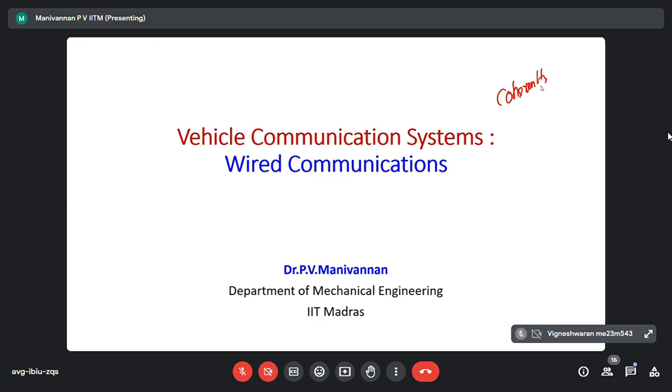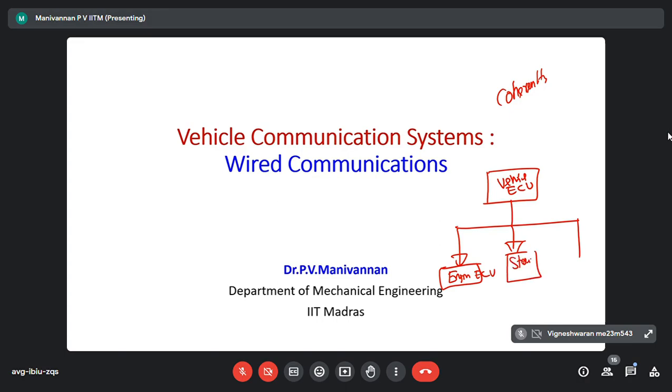There is no pressing of the accelerator; it directly gives an electrical command signal. It will give control to the engine control ECU to inject more fuel and accelerate, or reduce injection. But please note that injection is not controlled by the vehicle controller. That's what I'm talking about. You have a vehicle ECU. This ECU is going to control 3 more. And the main one is this, right? So the engine ECU, the steering ECU, and finally the brake ECU. We are talking about ABS. These 3 are going to control the engine.